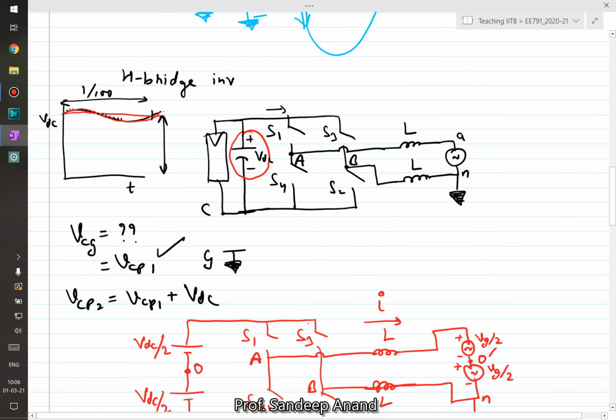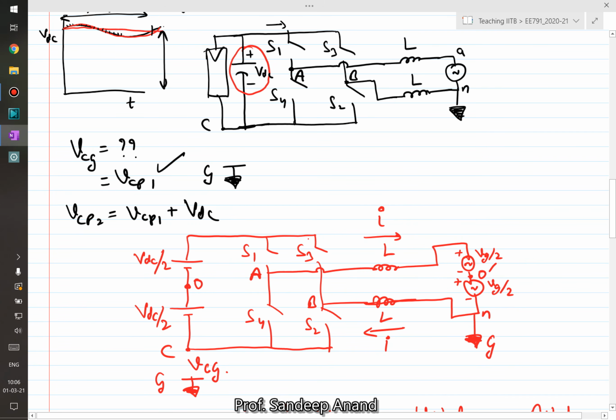And therefore when we talk about solar inverters, we do get restricted, and it's not that any circuit topology can be used for solar inverter application, right? Leakage current being an important aspect limits the usage of some of the circuit topologies. Some of the circuit topologies could be used, but some other topologies are not suitable for this application.